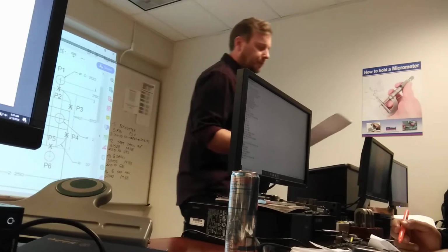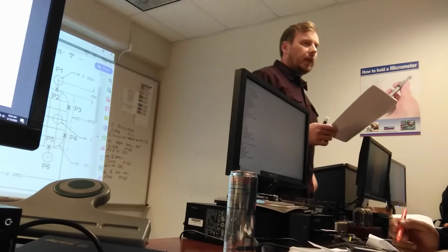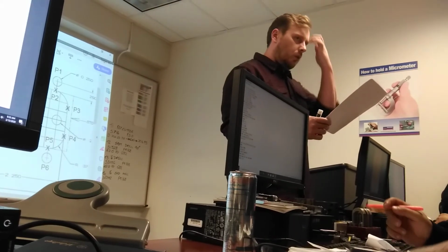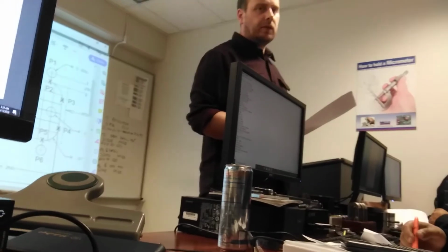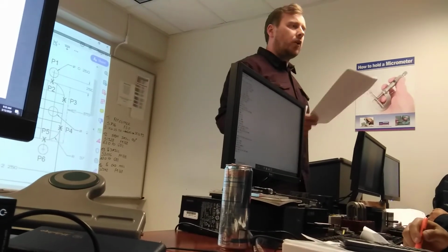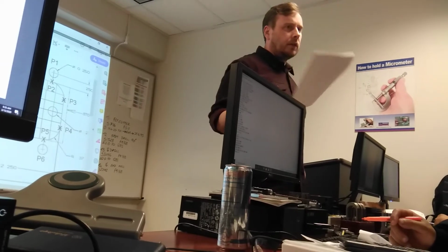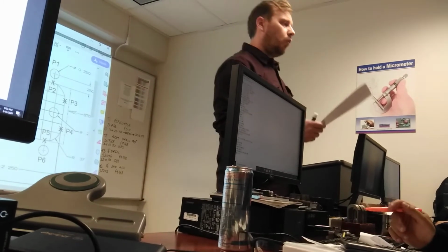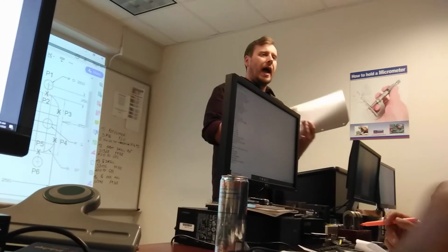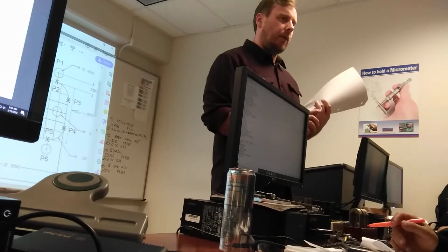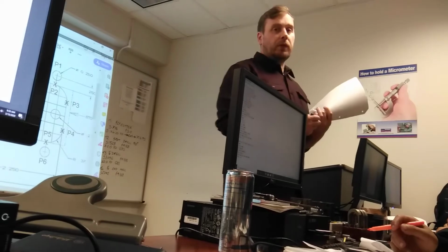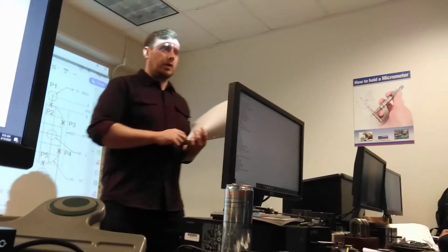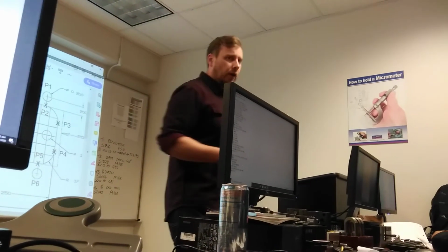Restriction number 3. It does not work if you try to do cutter compensation with a G2 or G3 move. So you can't put G41 G2. It does not work. You have to use G01. So whenever you activate cutter comp, it has to be with G1. Or G00. But if you G0 onto the part, what's going to happen to your tool? Oh, yeah. You're going to crash the tool. So just use G1. Forget about G0.